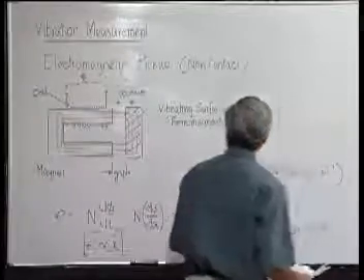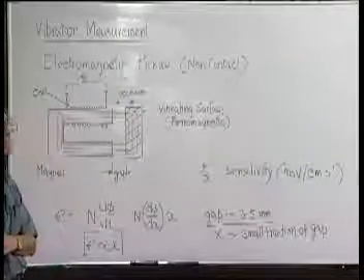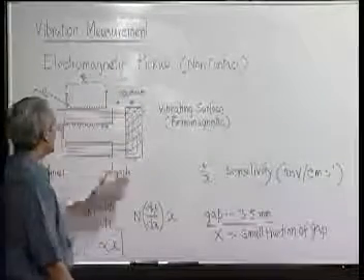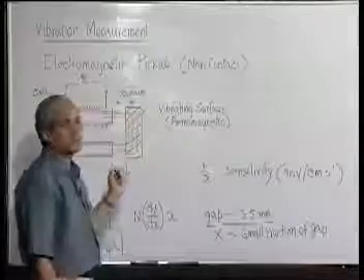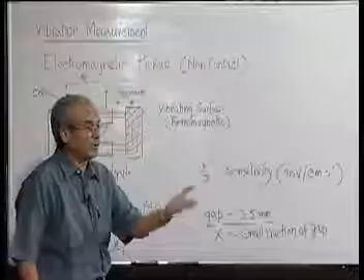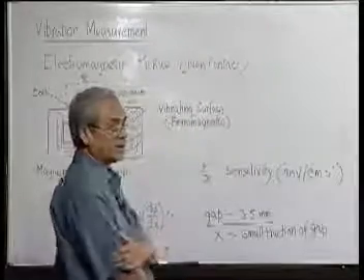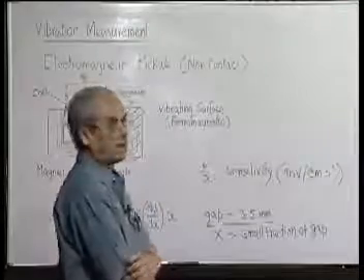Another point we have to keep in mind using a ferromagnetic pickup is that the material has to be ferromagnetic. There can be an object which is vibrating and we want to measure its vibration, but it is not made of ferromagnetic material, say plastic or brass, not steel.